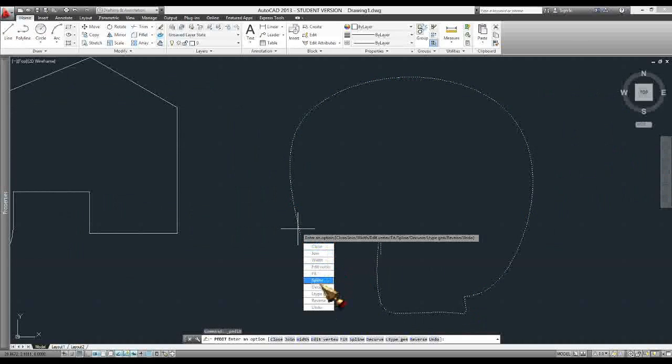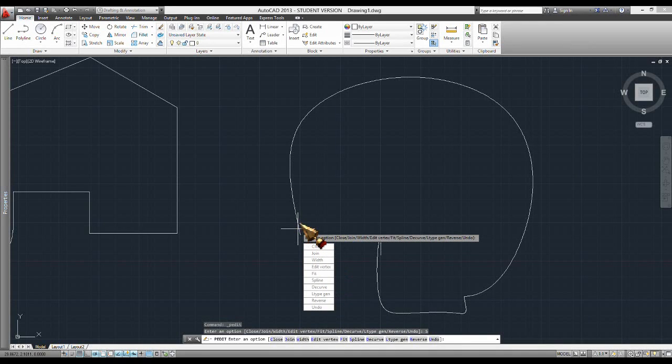Next thing, I'm going to try to go back. If you try to go from spline to polyline using the spline edit command, it'll actually convert it into a polyline, so that if you edit the now polyline, you have to use the pedit command, or polyline edit.